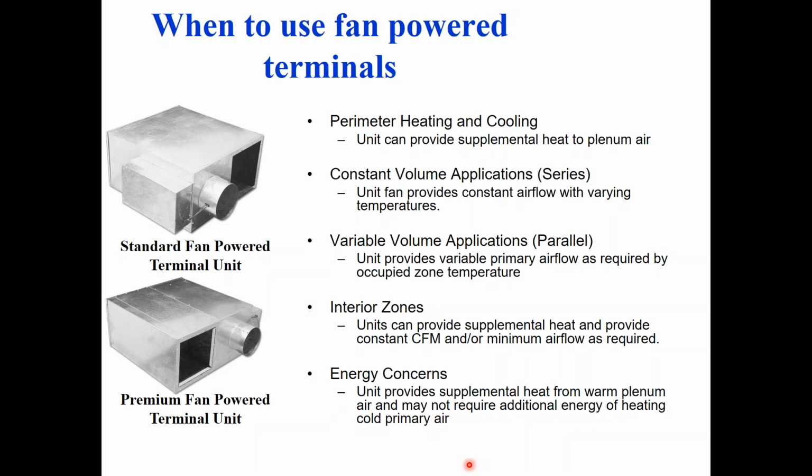All right, now we got fan-powered boxes. So like the other types, they come in a standard and in a premium, and obviously the premium costs more. It's better for sound, better for mixing, etc., and we'll talk about that. And then they also come in flavors of series and parallel. So a series fan power box has constant airflow during the occupied hours, constant airflow, and the fan never shuts off. And I'll explain how that works.